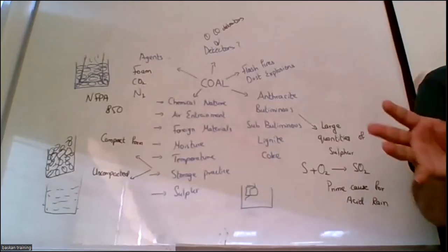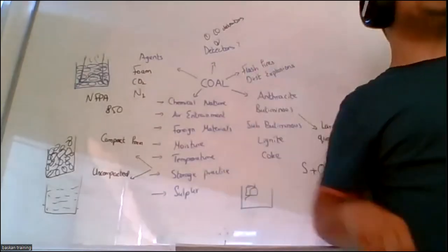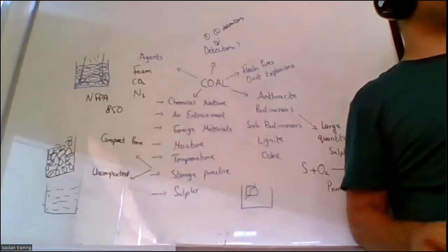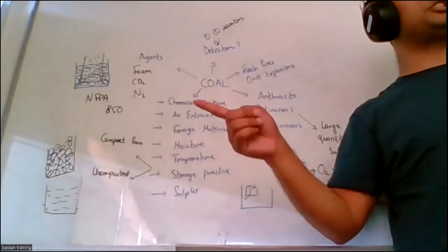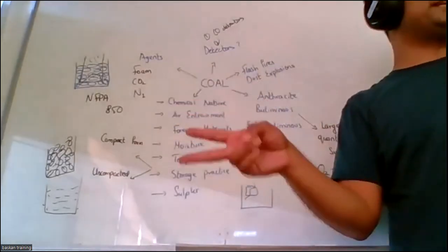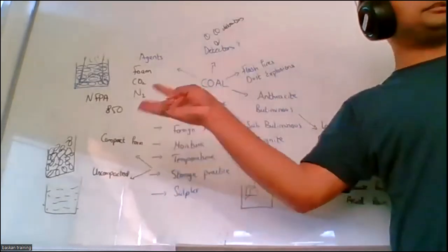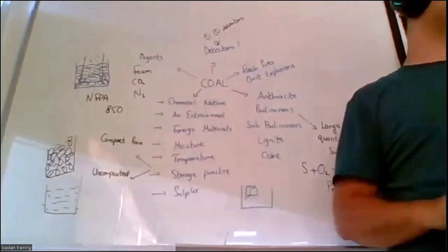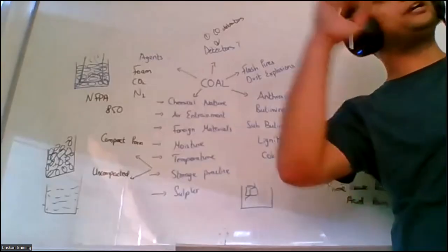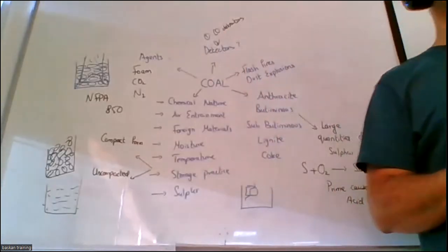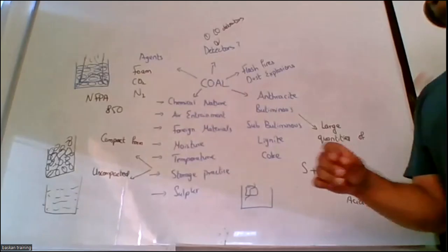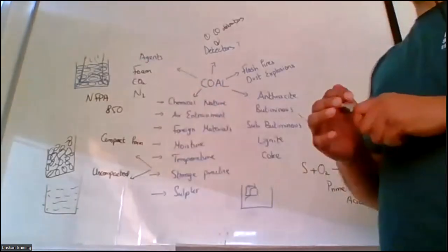That is why we jump back to section 2, temperature measurements. What are the techniques that we have discussed? 4 measurements. Liquid expansion cannot be used here. Bimetallic cannot be used here. Thermocouples, and pyrometers for radiation. So we have to go back to the basics and devise the solution that is available to us. So we use thermocouples.